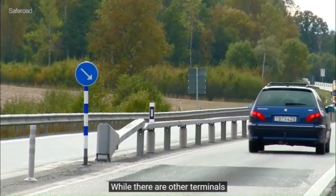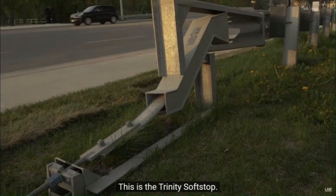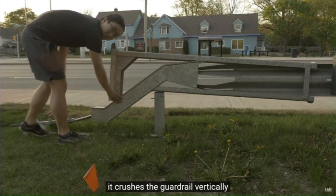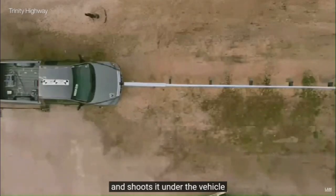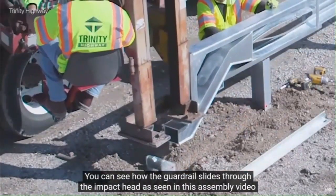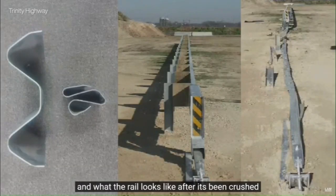While there are other terminals, I'm going to talk about one more because it's cool. This is the Trinity Soft Stop. When struck head-on, it crushes the guardrail vertically, pulls it through the impact head, and shoots it under the vehicle. You can see how the guardrail slides through the impact head as seen in this assembly video, and what the rail looks like after it's been crushed.